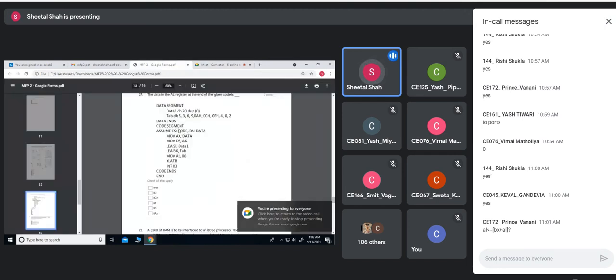So you can see that BX is pointing to this offset value, then it has to be summed with 6. So 0, 1, 2, 3, 4, 5, as well as 6. This value, that is 0F, would now be copied into the AL register. So at the end of this program, the AL register would have the value 0F.